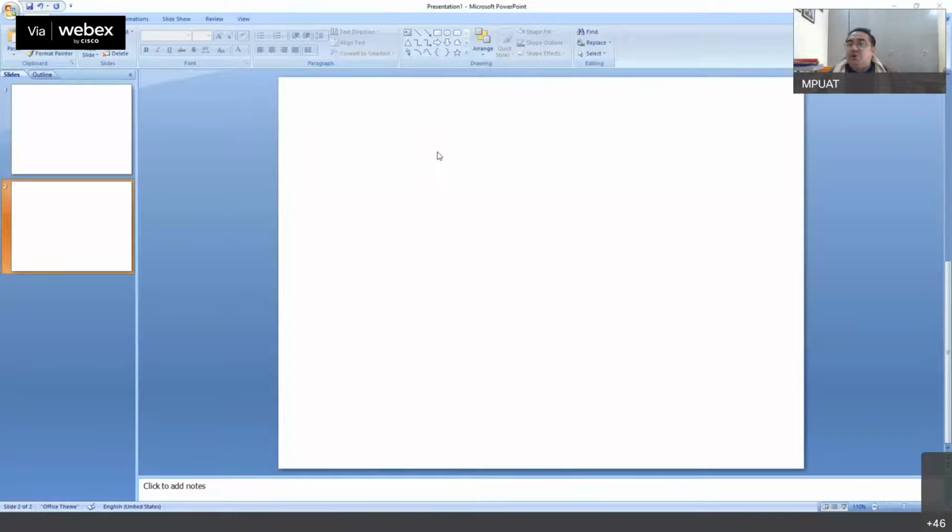Okay, so Adhikari has asked about the principle of mutual induction. Okay, once again. Transformer is first of all based on the principle of mutual induction. What is mutual induction? Since the word mutual is there, there will be involvement of at least two things. Two conductors will be involved. So let us draw these two conductors. This is the first conductor and this is the second conductor. Now say an AC current is flowing through this first conductor.